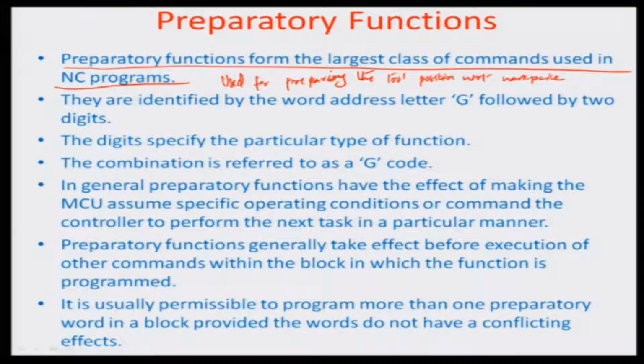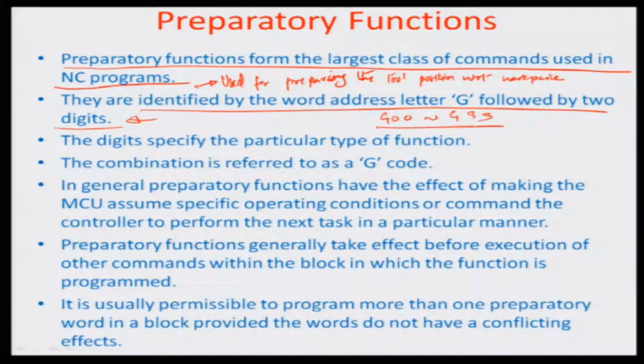Okay. So, this is how mostly these G commands or preparatory commands are used. You are preparing the tool position with respect to the workpiece. They are identified by the word address G followed by 2 digits. 2 digits mean that the controller can handle about 100 such G commands.